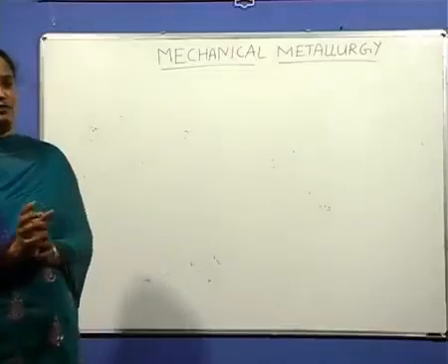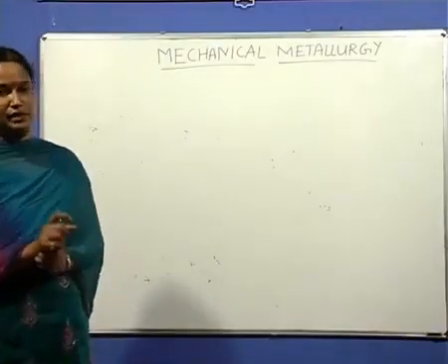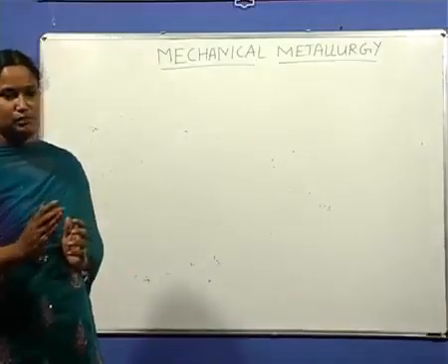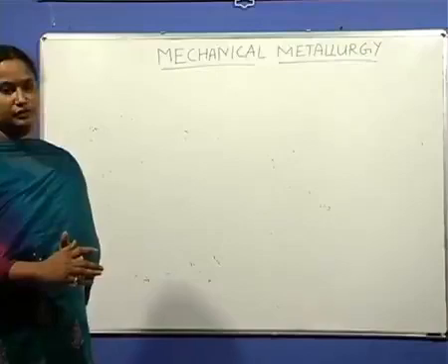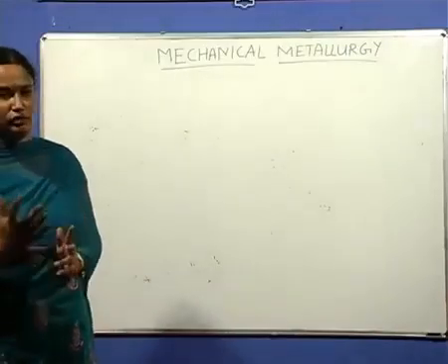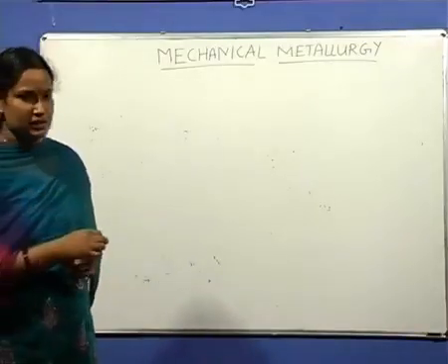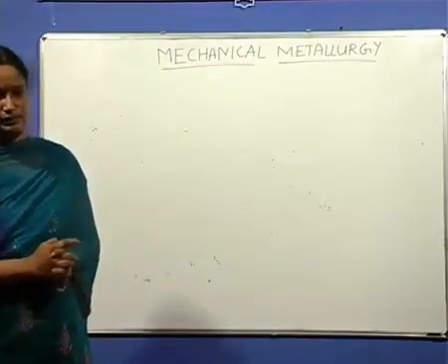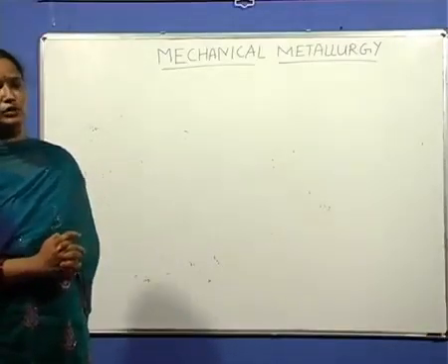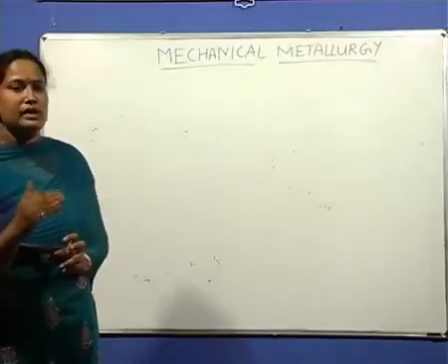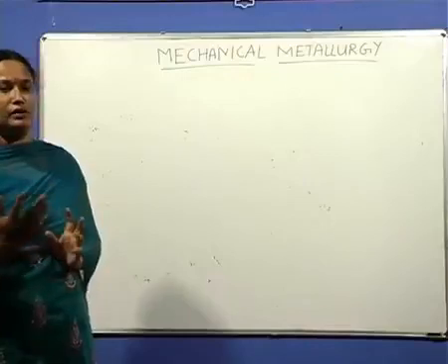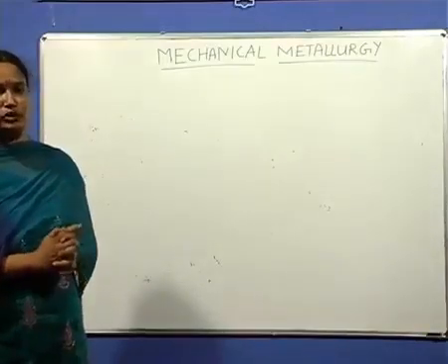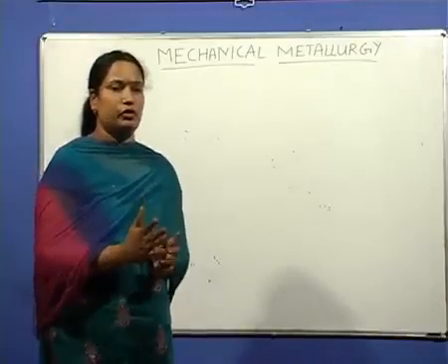Now in the introduction, I have discussed something about ductile and brittle materials. A material is said to be ductile if it undergoes some amount of plastic, permanent deformation before fracture. If a material does not undergo any, or only a very small amount of permanent deformation on a microscopic scale, and then fractures, it is called a brittle material. Normally brittle materials do not undergo plastic deformation. Upon increase in load, they simply fracture before undergoing any gross plastic deformation, whereas ductile materials undergo some amount of plastic deformation before fracture.